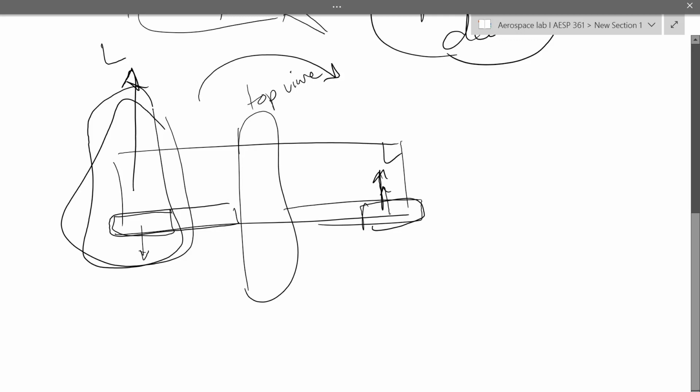But the direction of the increase in drag is going to be different for the two wings. So we will have higher drag on one wing, and we will have lower drag on the other wing. Since drag is only happening in, let's say this is the y direction, this difference is going to cause a rotating force in one of the directions, and that is going to cause yaw. But this is not something that we want. This is called adverse yaw.